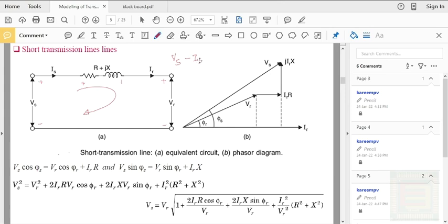All these terms, Vs and Is, are in phasors. And here it will be R plus jX, which is the impedance, and at this point you are meeting a drop in potential, so the equation will be Vs minus Is into (R plus jX) minus Vr equal to 0, or Vs will be equal to Is into (R plus jX) plus Vr.